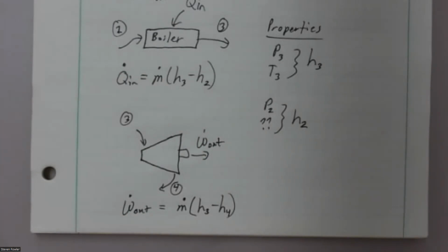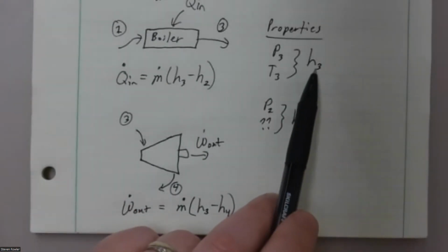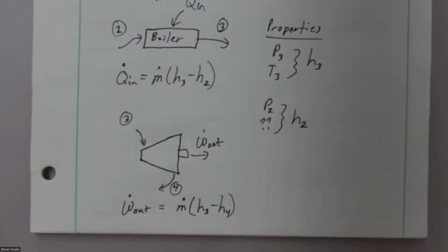I've simplified that and skipped a step there. So the power output is going to equal energy of the mass in minus energy of the mass out. We're neglecting kinetic energy because we don't have enough information to find it, and we think it's probably going to be negligible. And there's just enough other stuff going on anyway. We've already established I can find H3. Finding H4,